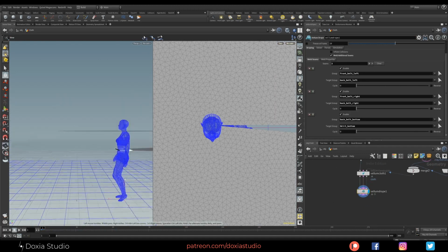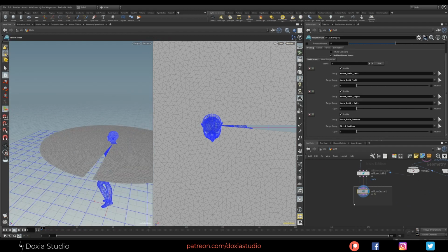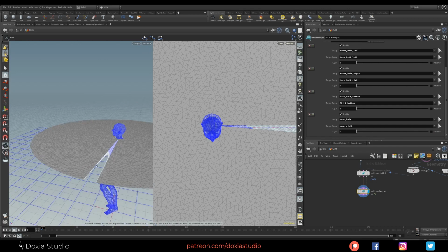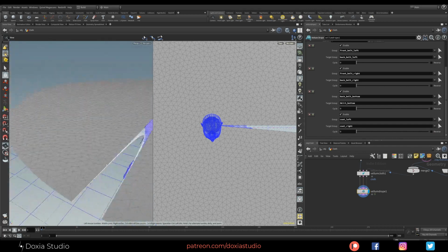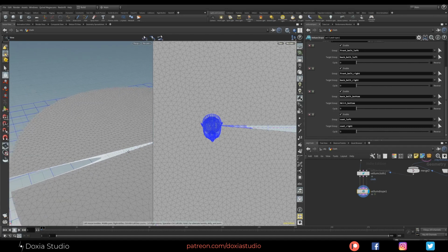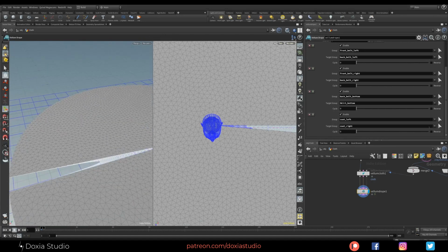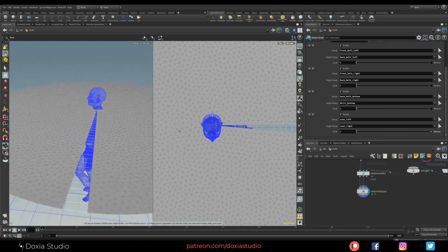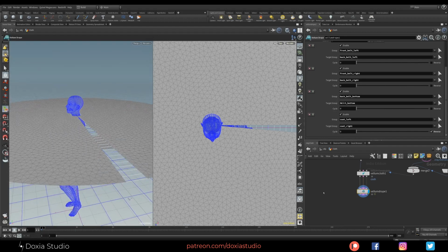And now we need to stitch this. A new group, let's go to drape, seam, new group, new seam, and let's go to coat left and coat right. As you can see, I mentioned this before, our seams are wrong, they are inverse, so let's check this reverse checkbox. Now everything is correct. Pretty cool, and let's play our simulation.